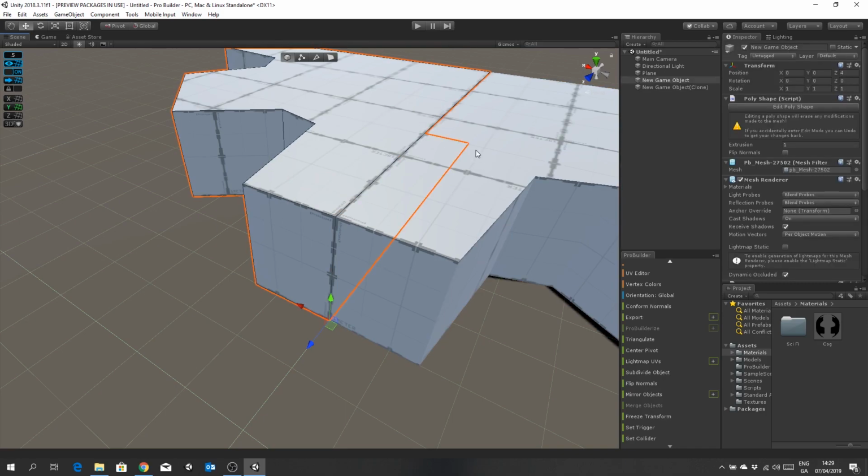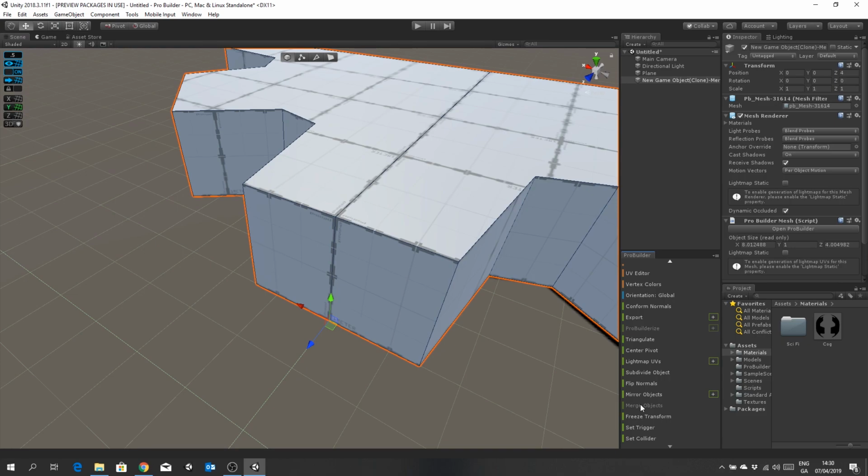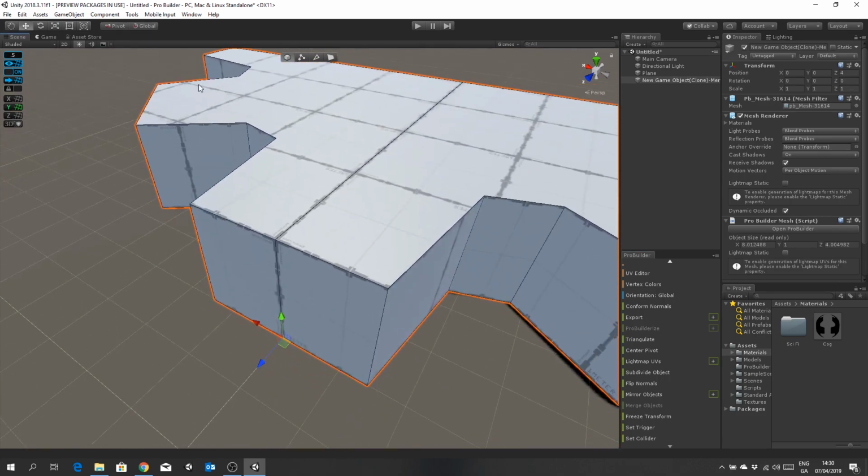Okay, so pick one of them, hold down Control, pick the other, and click on Group. Where is it? Is it Group? Where is it? Merge. Sorry, Merge Objects. There it is, in the green section. So now that's one object. The thing is, though, it is one object, but we're still seeing separate geometry, so we need to fix that.